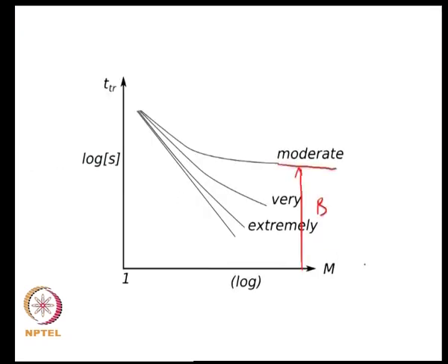So, also for simplicity we can assume that the rates at which your reset or your trip action is occurring are constant trip rates or reset rates. So, depending on the time required for tripping, it is going from a point of normal condition to a trip condition, and if the fault current goes away for some reason, then it is going at a constant rate back to the normal condition. Okay.